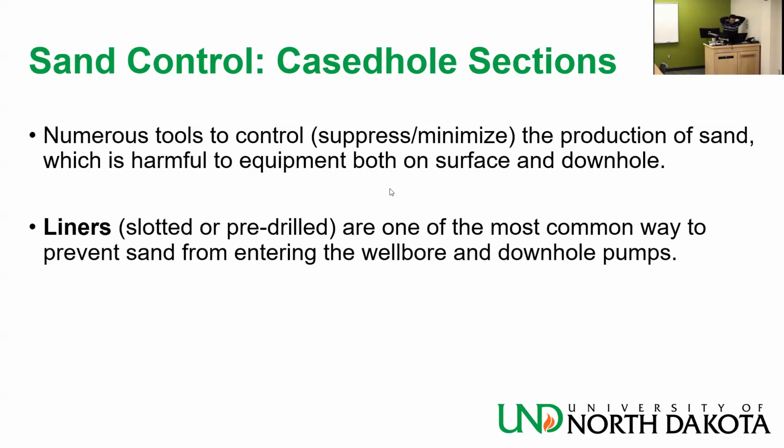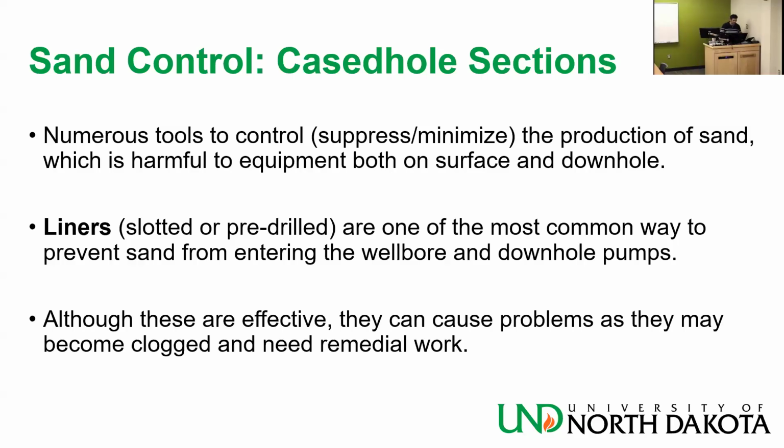Numerous tools exist to control, i.e. suppress, minimize, the production of sand, which is harmful to equipment, both on the surface and downhole. Liners, slotted or pre-drilled, and we're going to see pictures of those, are one of the most common ways to prevent sand from entering the wellbore and downhole pumps. We call that fines migration. It can be terrible for your equipment on the surface, as well as downhole.